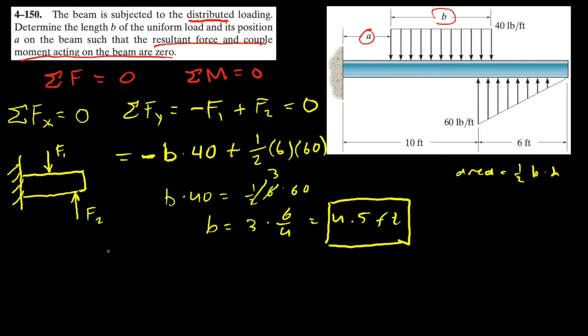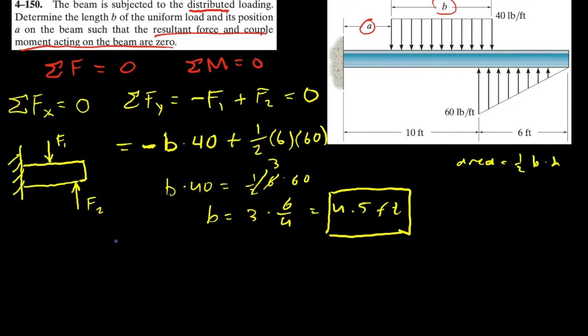So in order to do that, we need to understand where these point loads act. So we're talking about the distance here and also the distance here. For rectangular loads and triangular loads, when we simplify those distributed loads, where the equivalent point loads act is different. So the way we calculate this guy is different from how we calculate this guy.